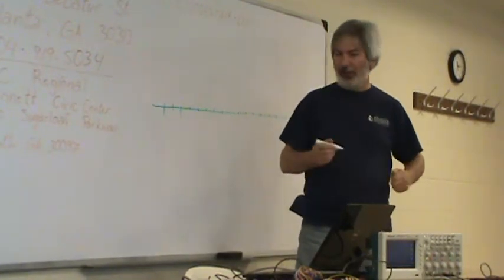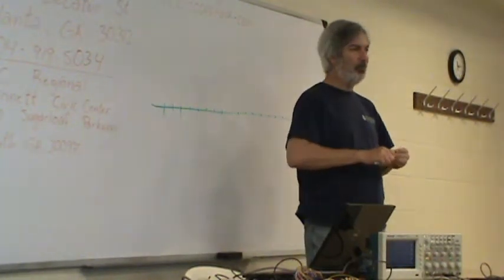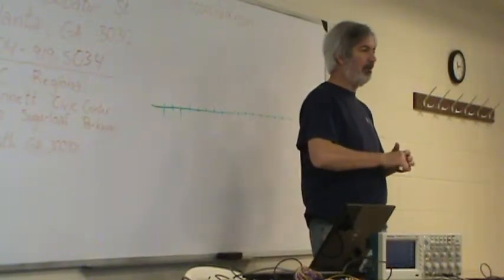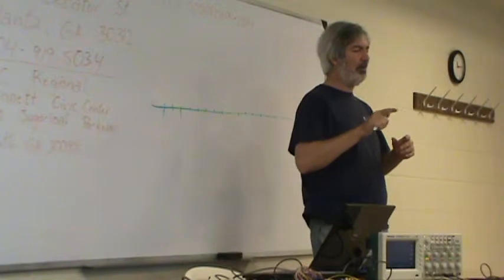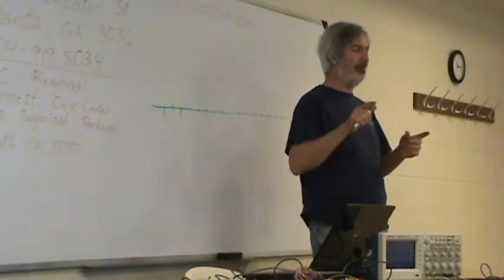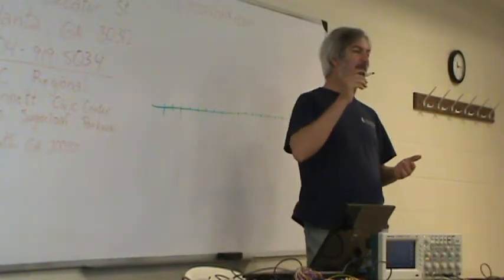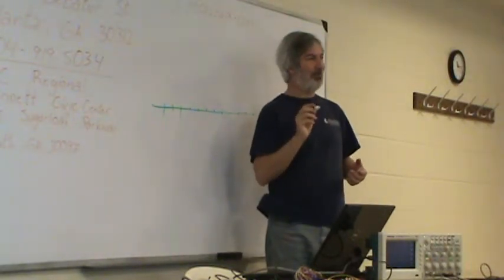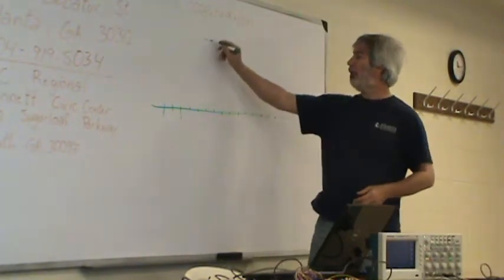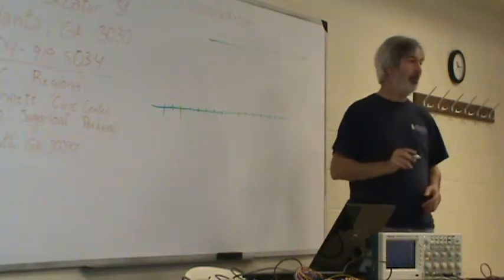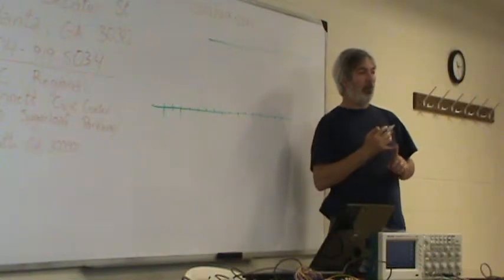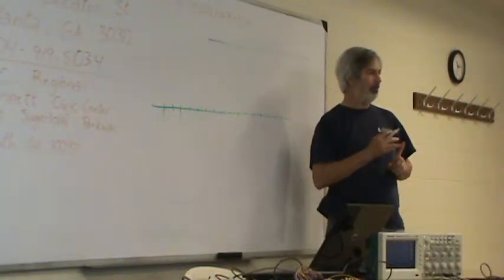But if you go and scope out a transmit pin, but it turns out it's actually a receive pin, on your scope, all you'll end up with is a straight line. Immediately you know, okay, I've got one of two problems. Either I'm on the wrong pin, or I haven't got my serial port running correctly.